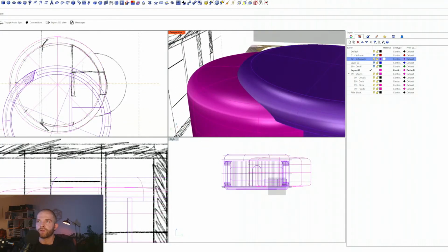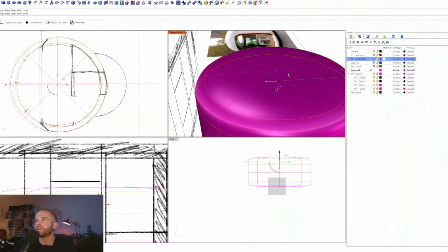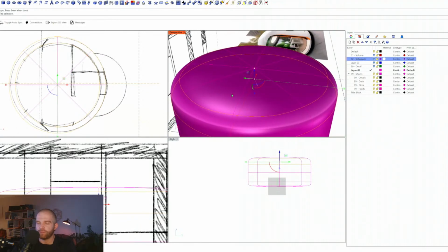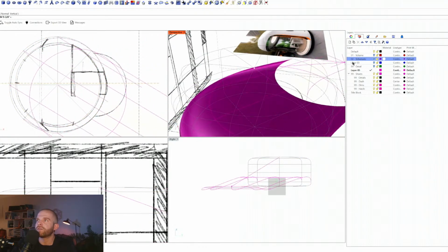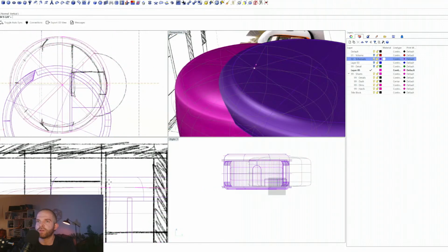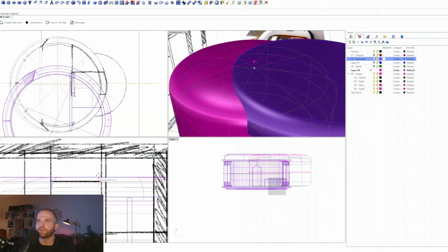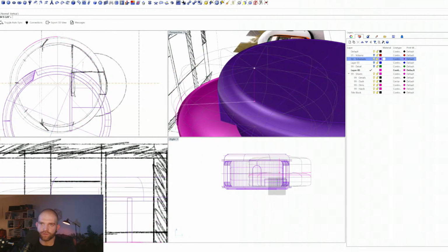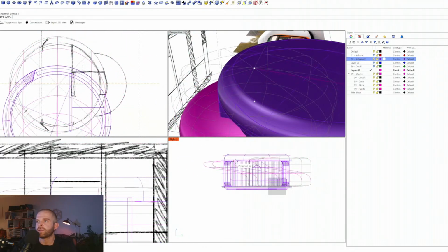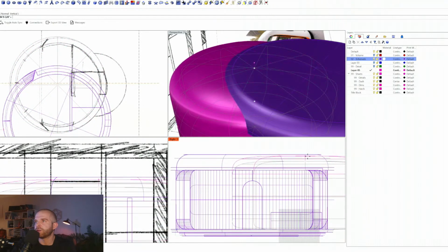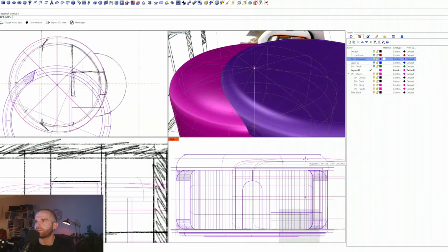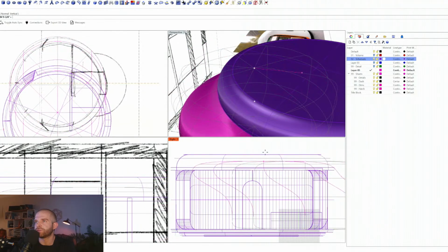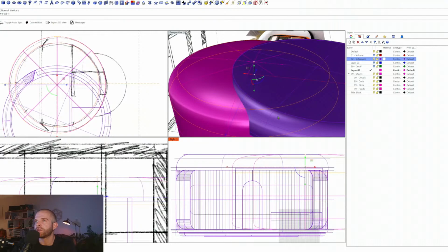I can also, once again, be more precise than just what I'm doing. Do that one more time, but I'll do the move command and I'll select off that vertex. I'll bring this back. I'll hold shift so that I'm locked in, and I want to turn off all snaps except for projection. So that if I hold shift, I'm just scaling up and down, and I can boop, snap to something that's there without dragging the entire geometry up against it. There we go.